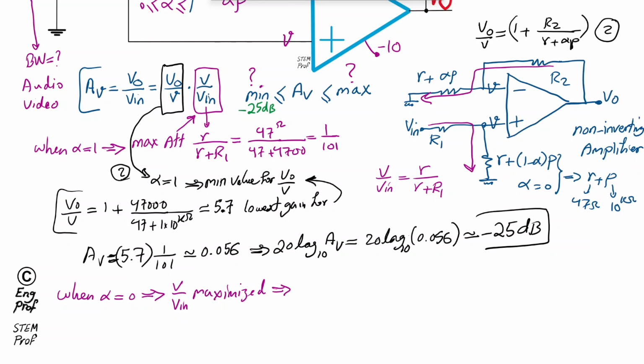So we get V over Vn equal to, so the transfer of V in to V at the positive terminal and negative terminal as well, roughly, as I said, we have 10 kilo ohm approximately, and then we have 4.7 kilo ohm, and there is a voltage division between them. So 10 kilo ohm plus 4.7 kilo ohm. So effectively, we have 10 over 14.7 approximately.